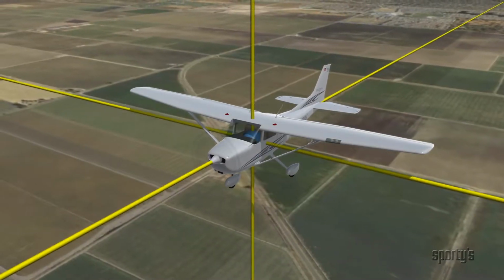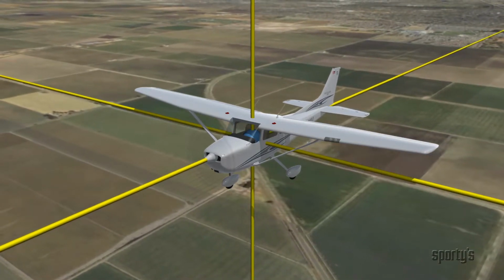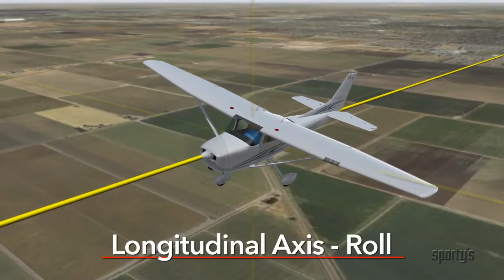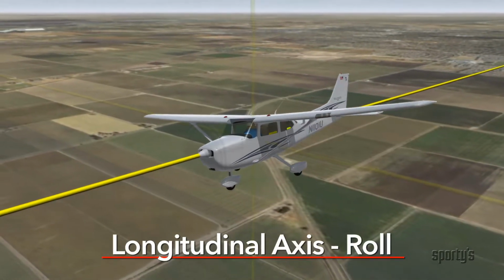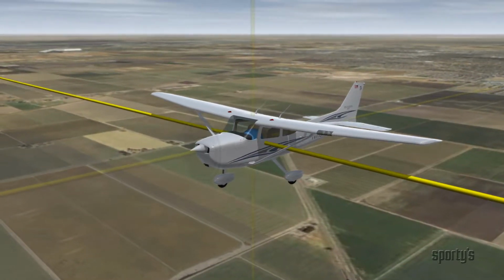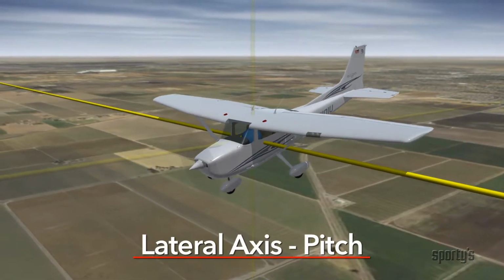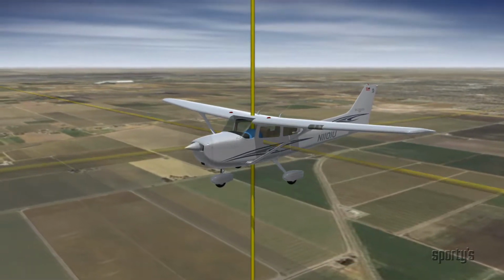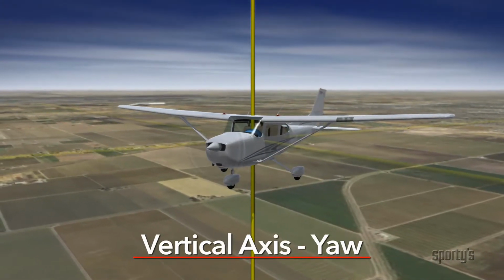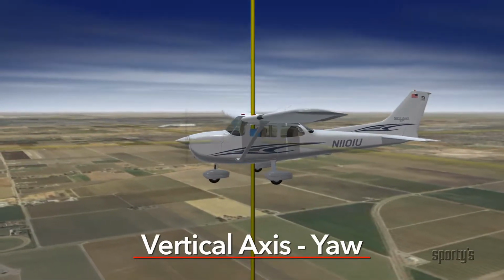An airplane in flight is free to rotate around 3 axes, which pass through the airplane's center of gravity. The axis which passes through the length of the airplane is the longitudinal, or long axis. Movement around this axis is called roll, or bank. The axis which passes through the fuselage at a right angle is the lateral axis, and movement around this axis is pitch. The remaining axis, which passes down through the fuselage at a right angle to both the longitudinal and lateral axes, is the vertical axis. Yaw is the movement around the vertical axis.